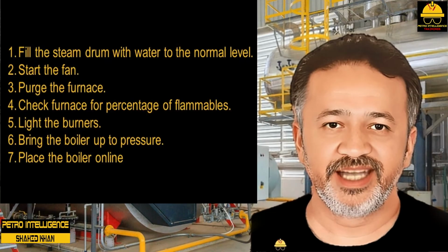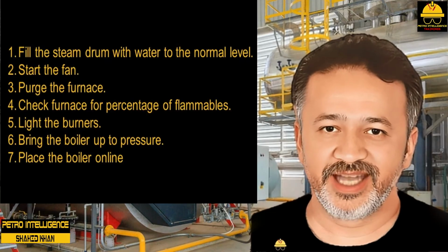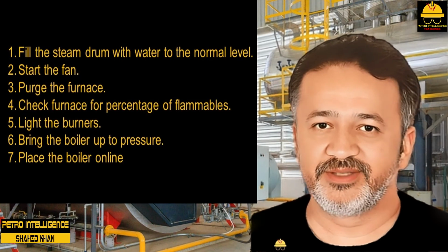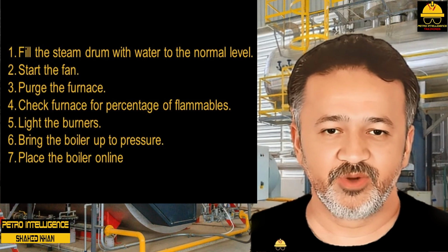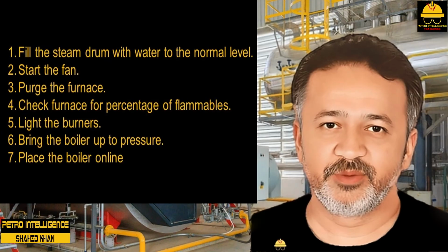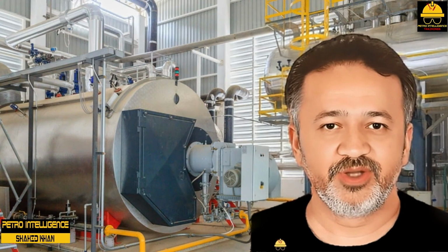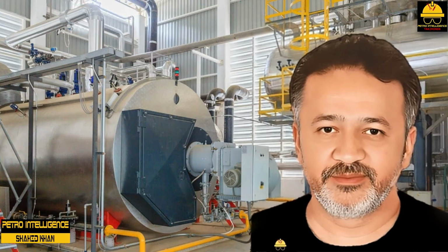The operator maintains good housekeeping and unit logs and checks fuel pressure and temperature and oxygen level. Finally, the operator monitors the pressure of the firebox and drum, the temperatures in the firebox, stack, superheater, and superheater temperatures, and ensures fan operation.